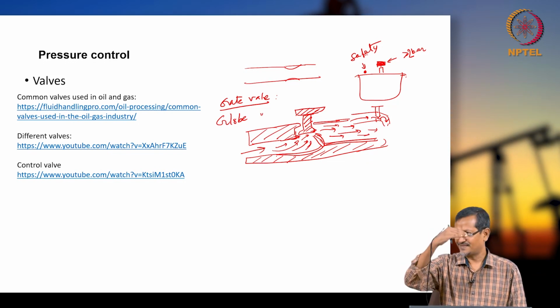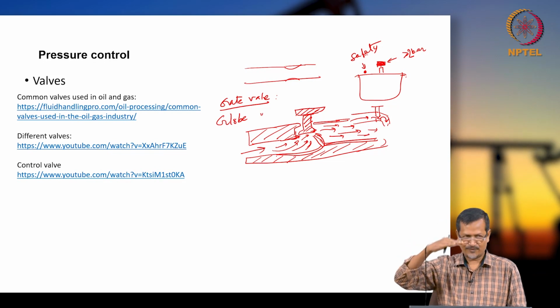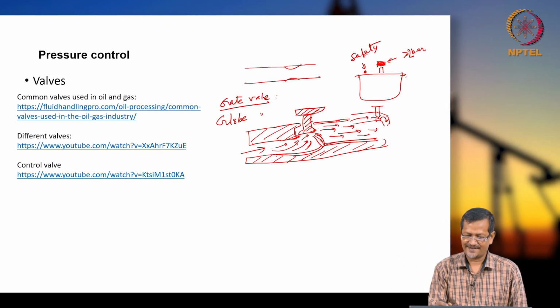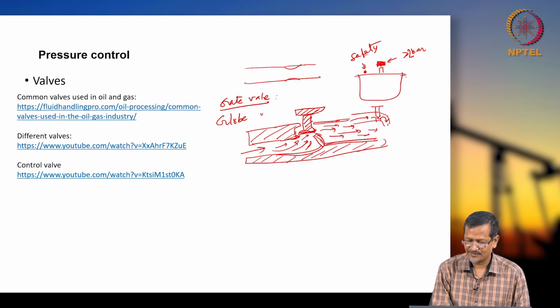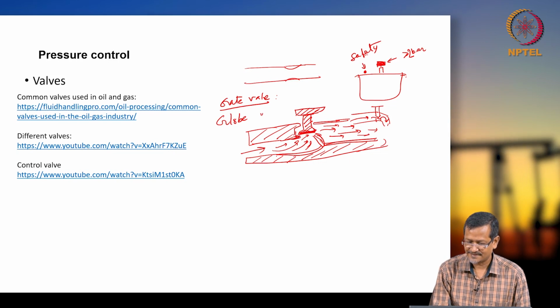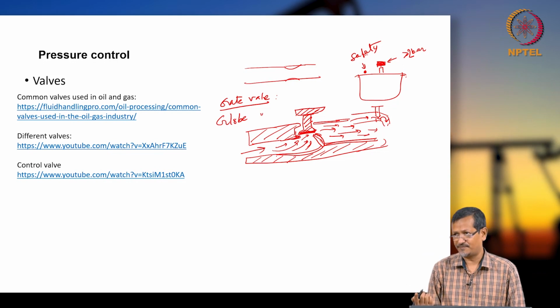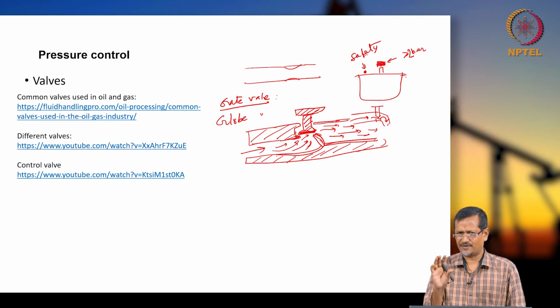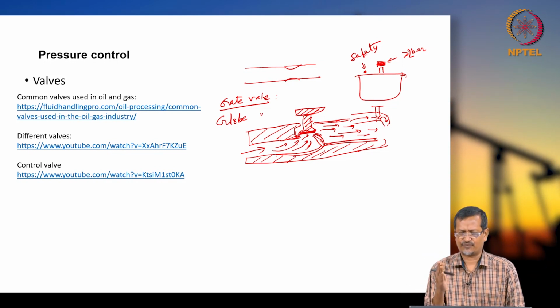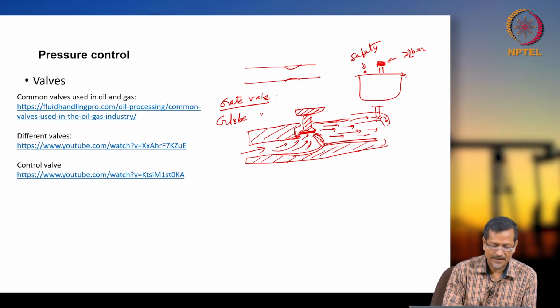open the path, and fluid will be flowing. If you move down again, it will be closing, right? So this one will be closing and opening. Move up and down, it will be closing. So this is called globe valve. Okay, so it's a different orientation actually. You are restricting flow. Another is called a plug valve.